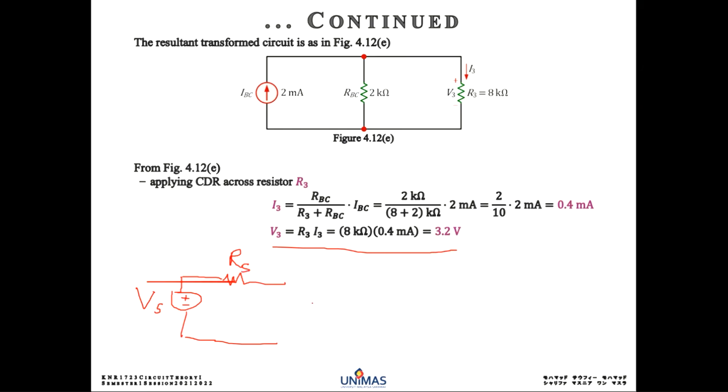You can always transform the source of the voltage here into a current source, but now the current source will be in parallel with the same resistor Rs. Itu saja. There is no fancy theorem, very fancy equation on this.